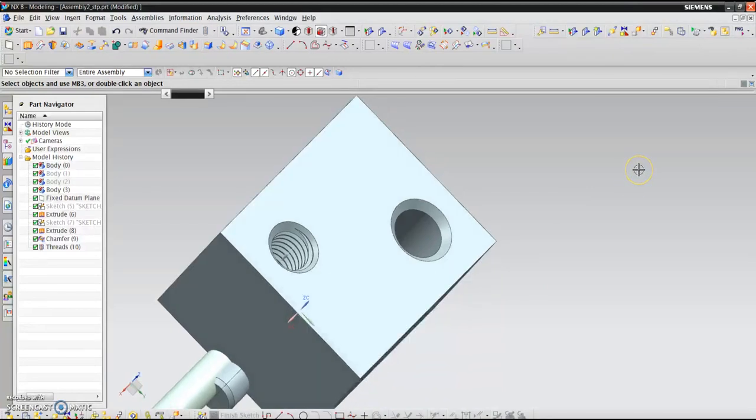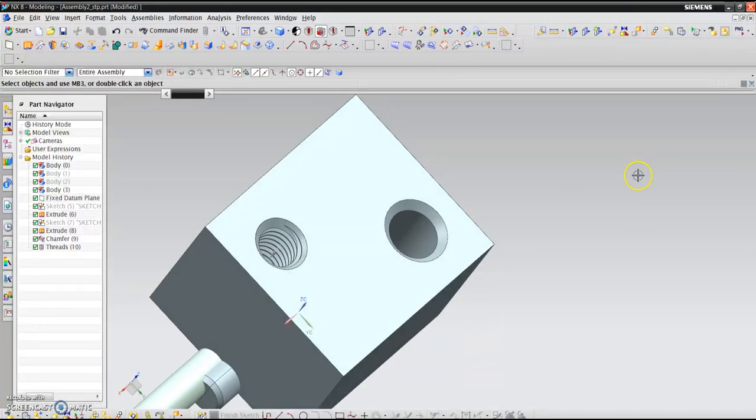The difference between the cut tap and form tap is based on the core diameter, or the minor diameter. For the cut taps, you take the major diameter and subtract the pitch, and you get the drill size used for the core diameter. That will have enough clearance for the tap to go and make the threads. If it's a roll form tap, you need to use a bigger core drill. For an M8 by 1.25 pitch, you'll be using at least a 7 millimeter drill size to make your core hole.